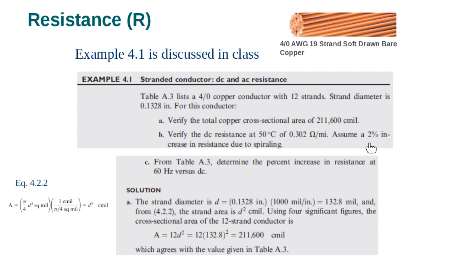What's spiraling? Spiraling is the spiral, like what you see here on the picture of the cable. It's not straight, it's spiraling. Therefore, the length increases because this is spiral, about 2% increase of the length.